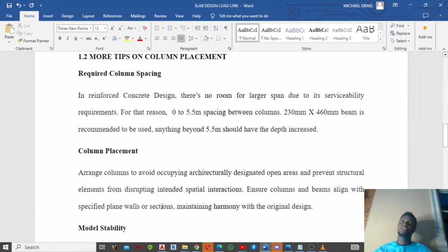What this means is this. If I actually want to do a very nice job, then I will try my best to make the breadth of the beam and also the breadth of the column to be the same so that they can align. You can stay perfectly well. Just like if the breadth of the beam is 230 mm, the breadth of the column should also be 230, so that they can align very well. Or you will see this by the time we start working on it.